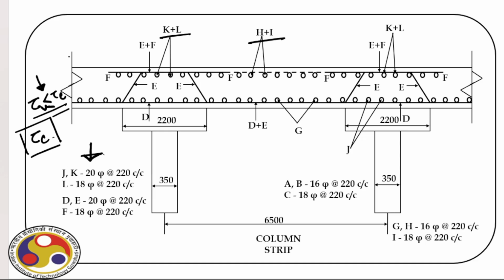You can design a flat slab with other panels and with other geometry of, say, column. The only thing you have to remember is to consider all the options for bending moment and shear force outlined here. And we have designed this interior panel using the direct method. You can go for a detailed analysis using finite element, which normally is covered in the 4th year of your undergraduate curriculum, and that's why it is not covered here. So for the time being, you can go for the direct options as prescribed in IS 456.